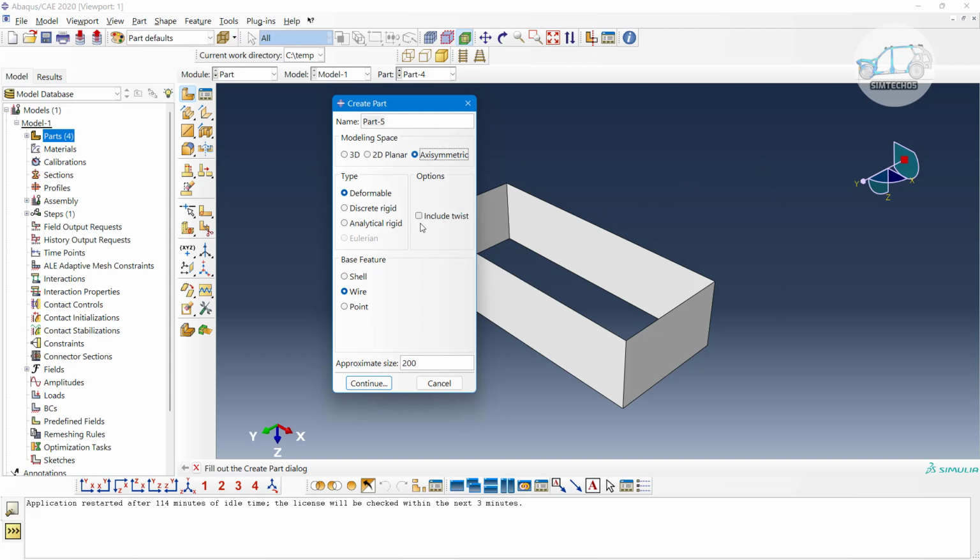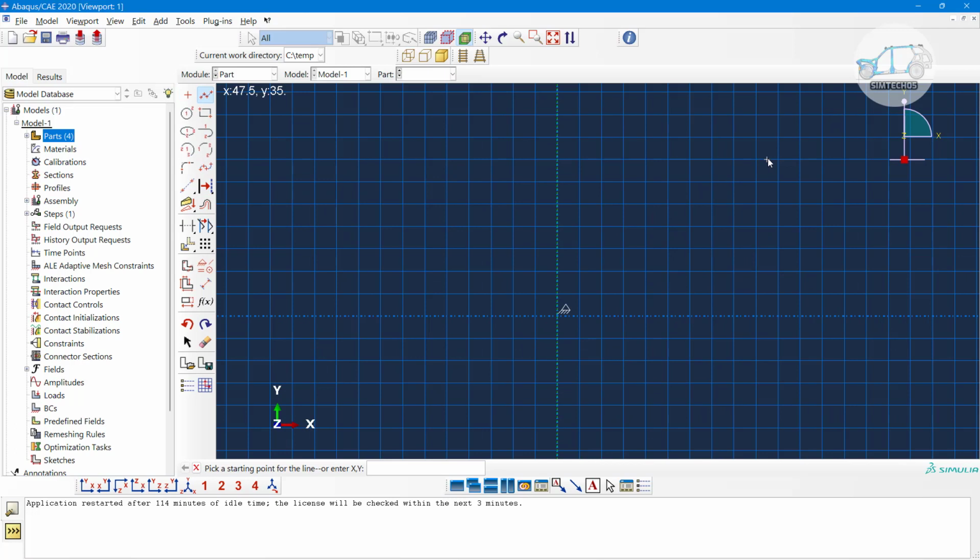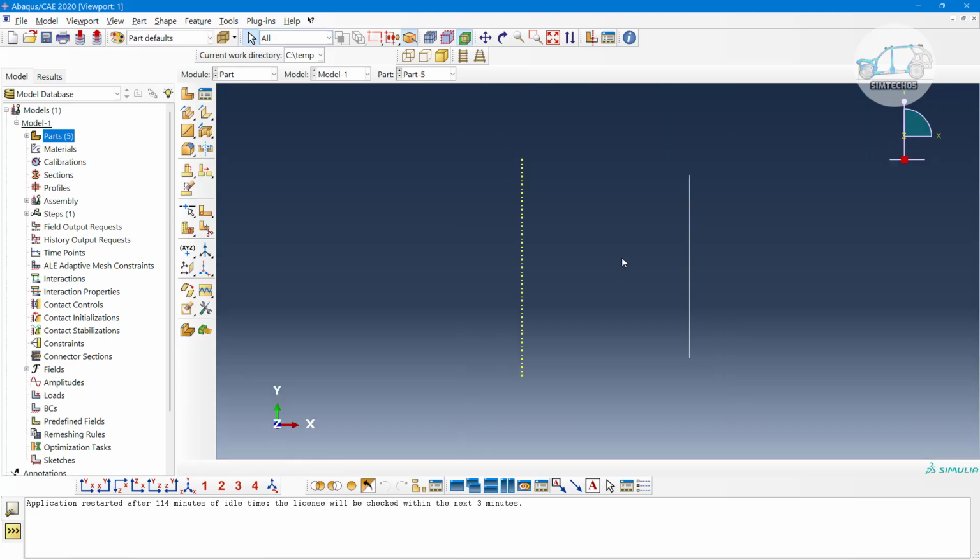And the axisymmetric wire, what that means is, just try to think about that. If this is the wire and this is the center of axis, and if I rotate this wire along the center of axis, this becomes, of course, a cylinder, but a surface form. So now this is the surface feature. It looks like a line, but it's a surface feature.